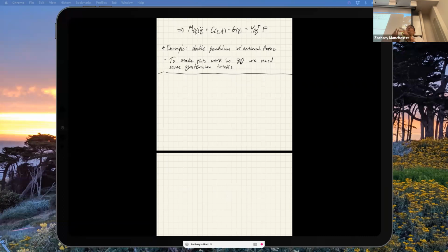The root of most of these annoyances is that there's no coordinate representation that actually corresponds to omega. I can't integrate omega from a gyro into anything meaningful without doing some weird stuff. Euler angles, quaternions, rotation matrices, none of those things corresponds to the integral of omega. We talked about this very early in the class. That's the heart of this. I can choose any rotation representation I want to write the kinematics down. But when I chain rule through the kinematics to get my velocities to plug into 1/2 omega transpose J omega, I need to get the omegas out of that rotation representation, which is always non-trivial.